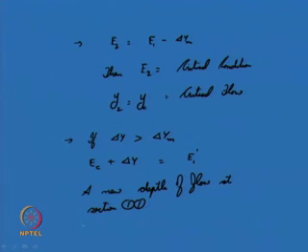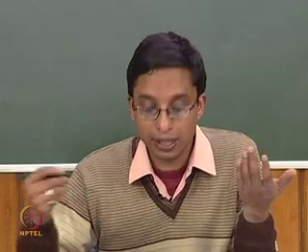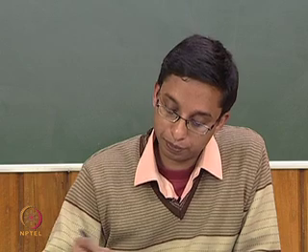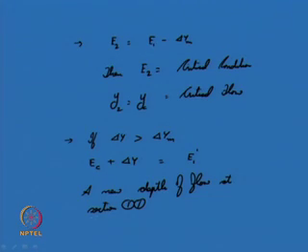If the hump height is still much higher, then the flow at section 1 changes its specific energy and it raises its elevation. So, at section 1 the depth of flow increases. So, this is an increased depth at section 1.